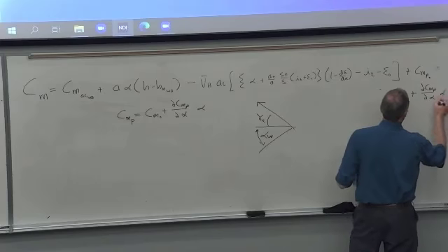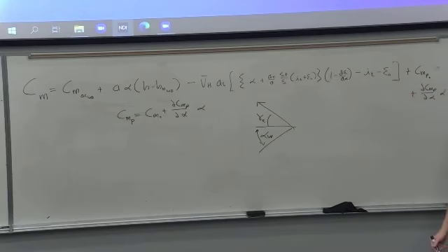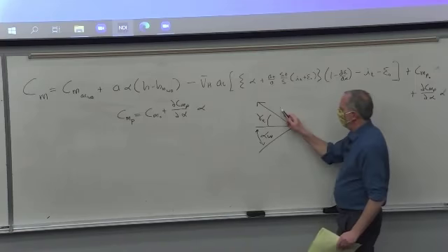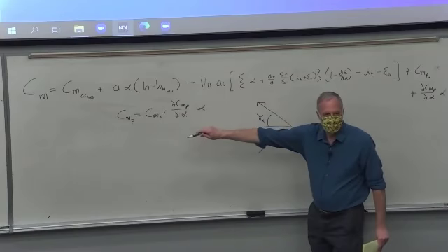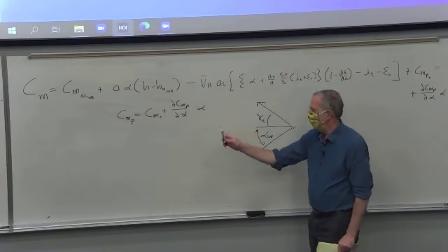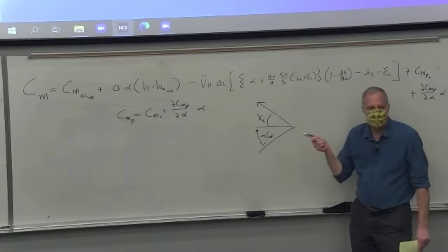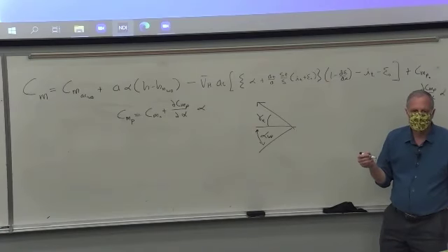And in all honesty, I'm including it so that you can see, well, yeah, the engine could produce a pitching moment. For most of the examples and the stuff we do, we just say that that's zero. That the thrust line is not tilted up so much, it's pretty much just straightforward through the CG, and that the drag is backward, and so the thrust just balances the drag, and you get no moment.